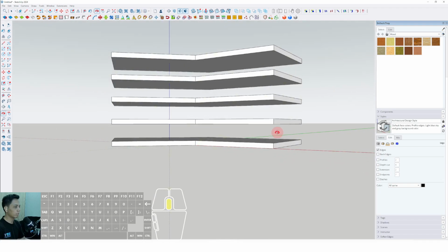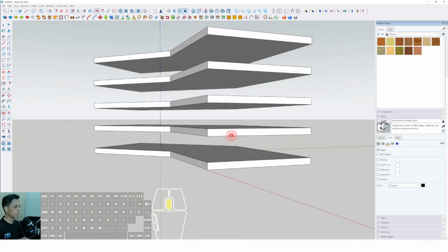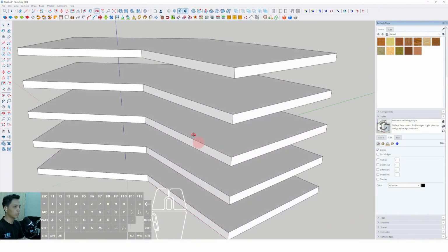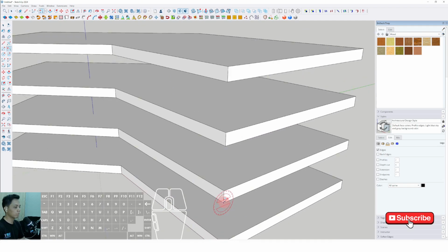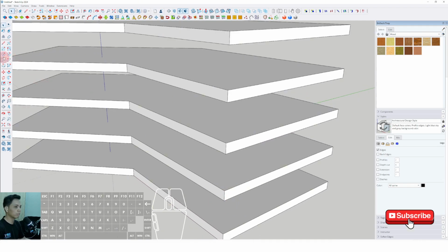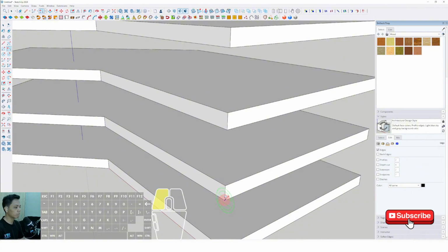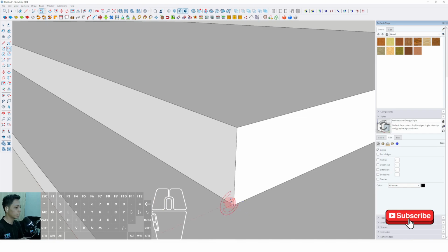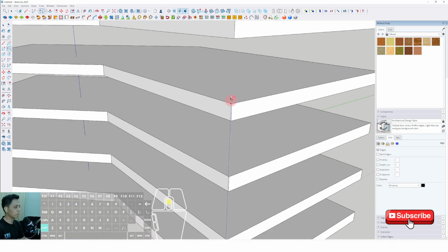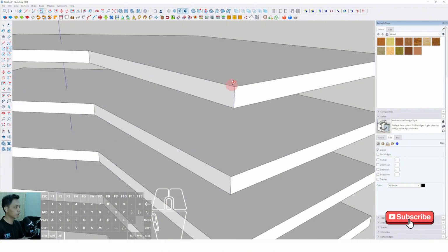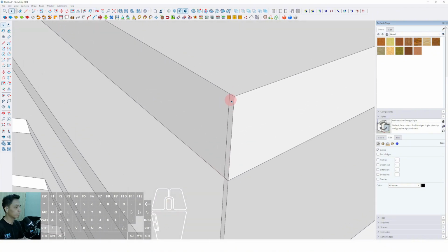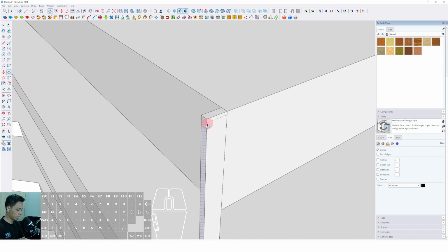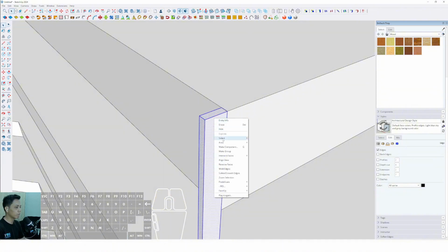Okay, well, now we can make this facade in the second floor, third floor, and fourth floor using a vertical frame. For the detail of the facade, we can select the rotated rectangle and click from this corner. Then we can set the width of this vertical frame and place it to this position. Okay, well, now we can select push and push it to the front around 200 millimeter or 20 centimeter.